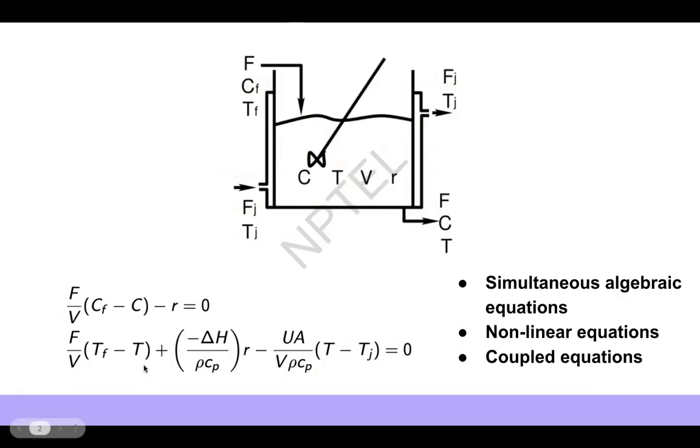In MATLAB, steady state equation solving means this equation that we have is a steady state equation because there is no d by dt term. Again, this equation is also a steady state equation because there is no d by dt term. So to get the steady state C and steady state T, you just have to solve these two equations together. And again, these two are nonlinear equations.